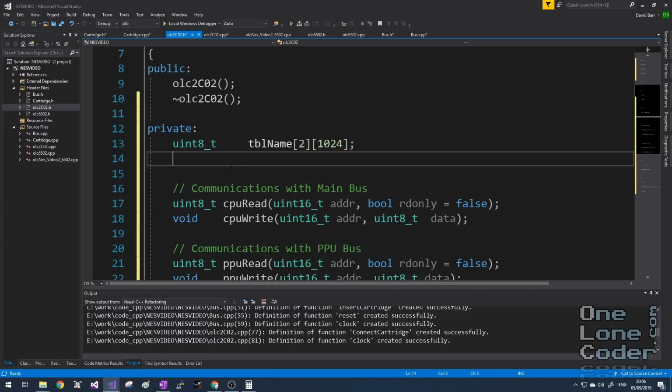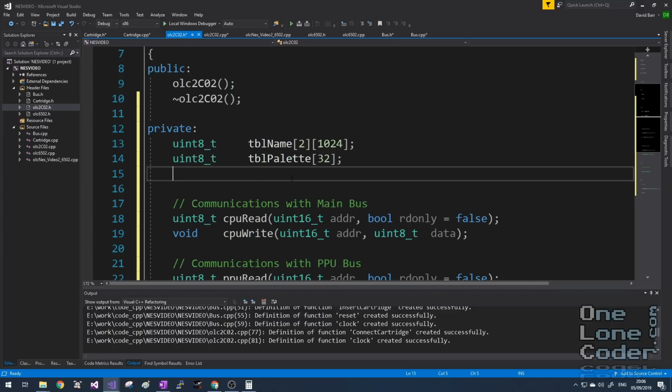There was a RAM connected to the PPU bus that stored the palette information. There are 32 entries. Now, I'm going to add something completely unnecessary, because I'm a little strange. I'm going to add two 4 kilobyte arrays that represent our pattern memory. This memory exists on the cartridge in normal NES systems, and normal NES emulators will do just that. And in fact, if you load up a NES game into this emulator, this memory will never be touched.